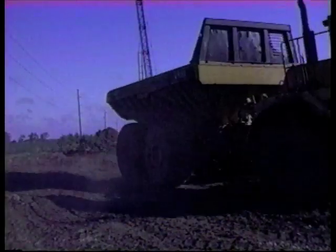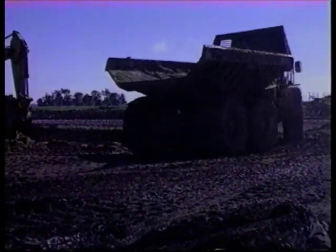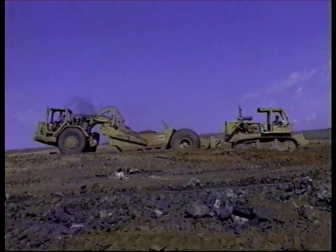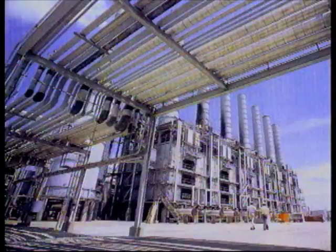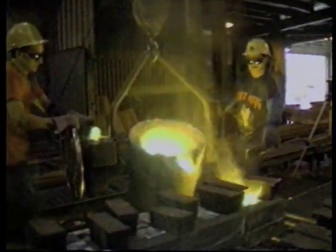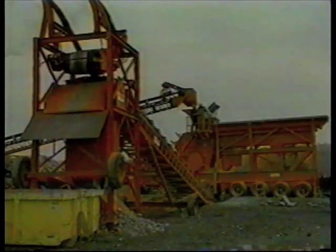Steel castings have been used extensively for dynamic loads. Steels are resistant to sudden failure because of their toughness, and steels are resistant to unexpected short service life because of metal fatigue. By varying the alloy composition, steel can handle high temperature and corrosive environments. Only steel affords this wide range of properties.